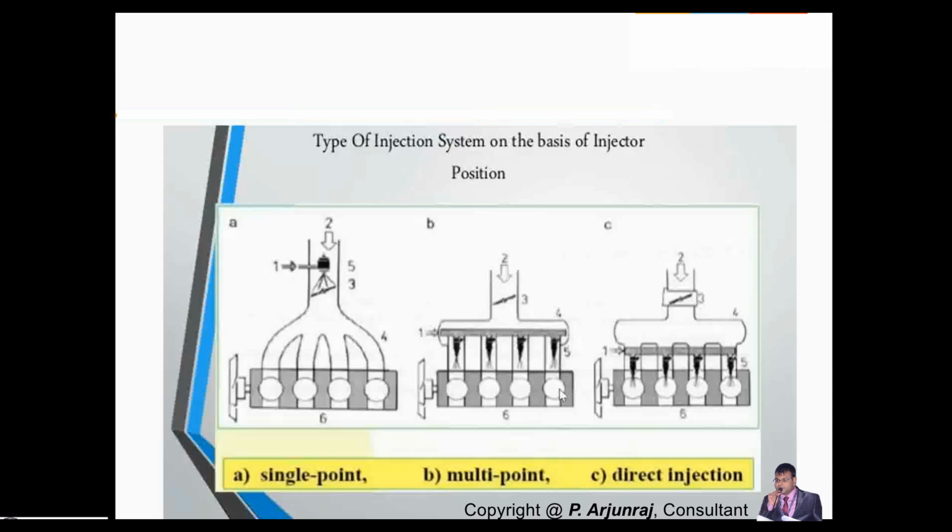Suppose, and again, the quantity of fuel getting injected into the system will also vary with respect to the engine speed. The last important type is gas direct injection, where the injection will happen directly into the combustion chamber, where you get advantages of emission and power output.